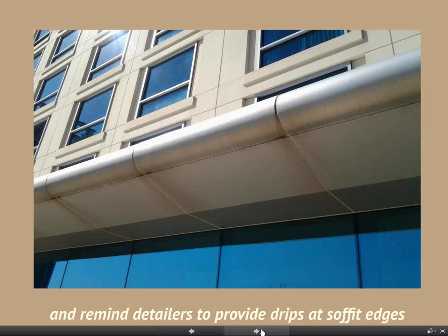This is a great example of what happens with those horizontal rounded edges like this, where the water just follows the edge around. This is a hotel that's, I don't think, 2 years old, maybe 3. There's no way to prevent the staining on the bottom surface of the round edge because the water's going to run and follow it. And the janitor ain't going to clean it. Right.